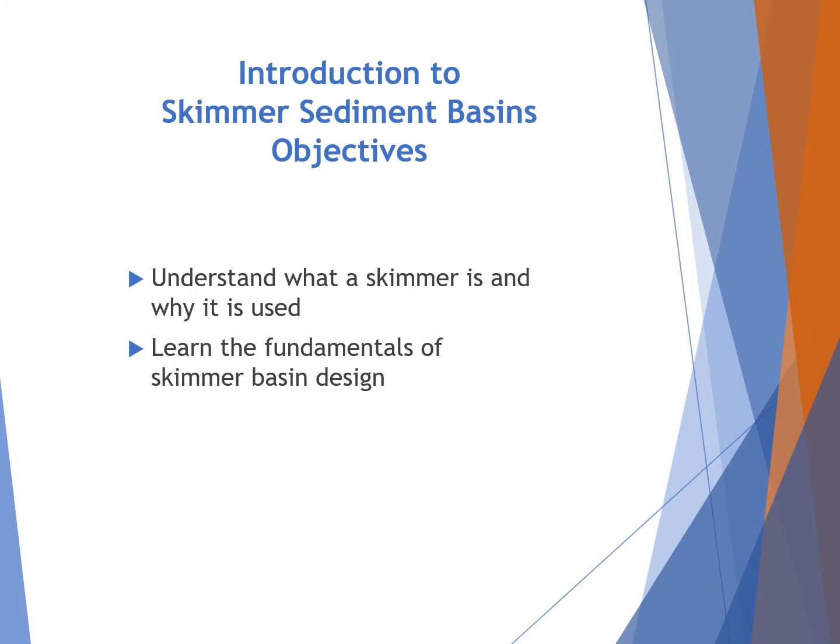Introduction to Skimmer Sediment Basins Objectives. This will be a short course to go over exactly what a skimmer is and why it is used, and also learn the fundamentals of skimmer basin design. We will also review just a few slides regarding the Marley float skimmer and specifics about incorporating that skimmer into your designs.